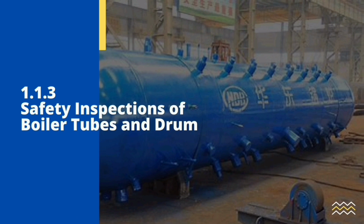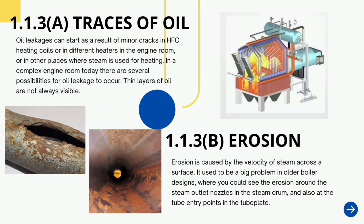Safety inspection of boiler, tube and drum. A. A trace of oil leaks can start as a result of minor crack in HFO heating coil or in a different heater in the engine room or in other place where steam is used for heating. In a complex engine room today, there are several possibilities for oil leak to occur. Thin layers of oil are not always visible.